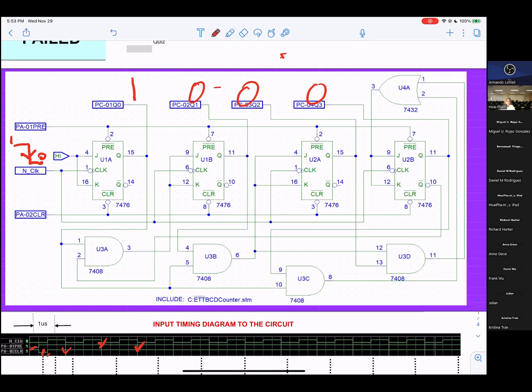It's hard to use the meter to see that signal. The thing is, when you use the meter to connect to U1 pin 1, you see nothing. The clock is already done. That's why you have to use the oscilloscope. But we have to add a few lines. I will let you know. Okay?